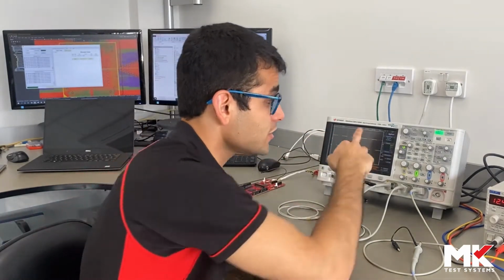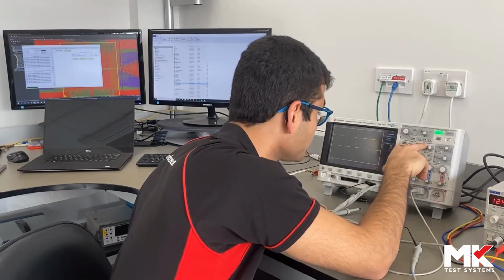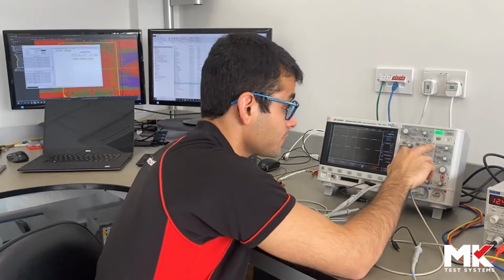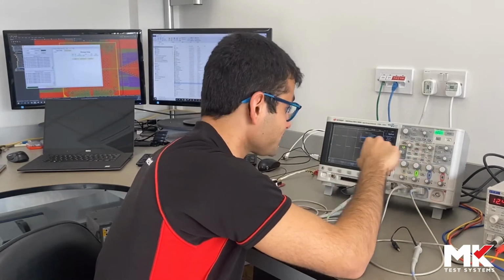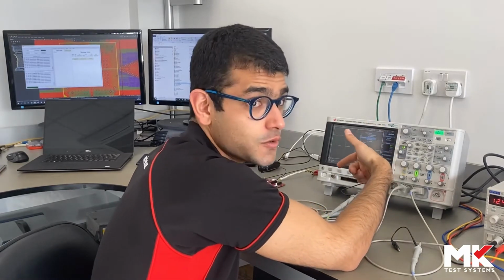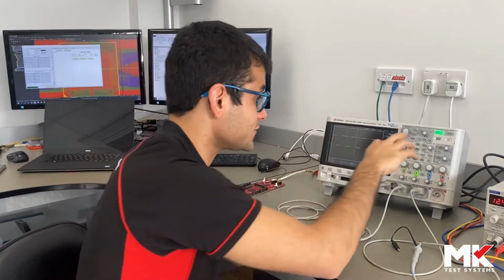First thing you start with is you look for the cursor button, which you'll find in the measurement area. Press on it. It's going to display 2 cursors, X1 and X2, which you can use to measure the displacement between them. Starting with X1, in order to set it up, press on the adjuster, and it's going to display a small tab that says X1, X2, or X1 and 2 linked, and there's also Y1 and Y2, and Y1 and Y2 linked.